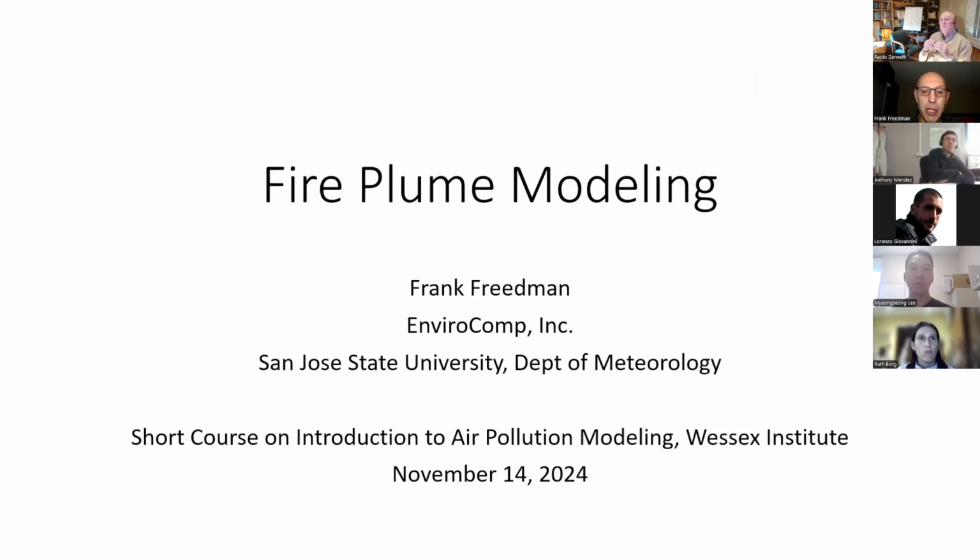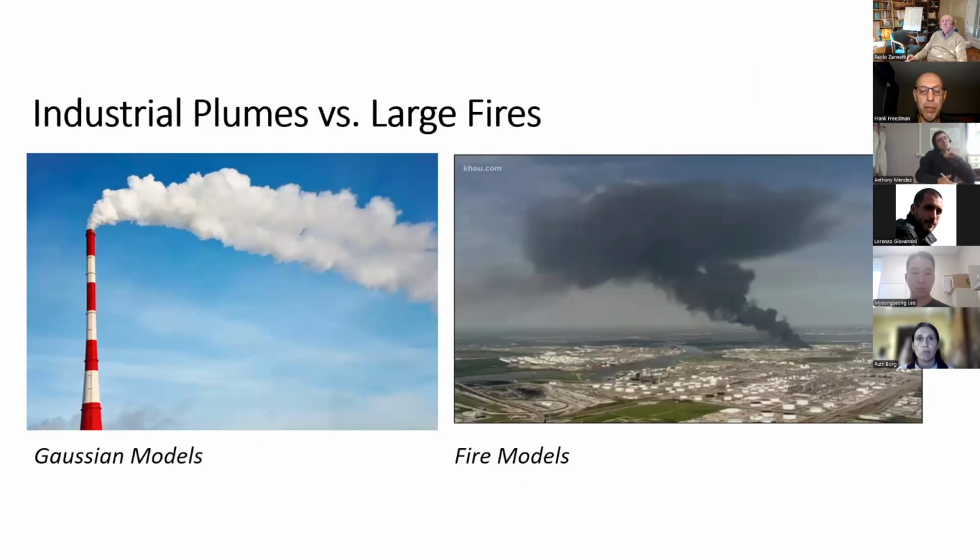So the background I have in fire is a combination of the current work at San Jose State I'm doing, plus a lot of the projects that I've worked on with Paolo that have involved dispersion from industrial fires, which is what we will talk about in detail today. So this picture here is a comparison of the kinds of plumes that can be modeled with dispersion models, and particularly with fires.